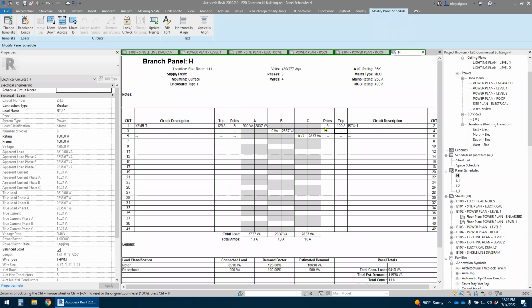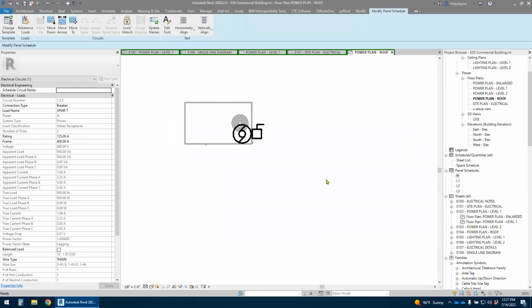I told you it wouldn't pull the information from anywhere. You also see that the way the family's set up, it's automatically dividing my load over the 3 phases. The transformer has a 900 and it's not splitting things up yet. So it's because there's only a 5 receptacle load. I don't think it would divide it over the 3 phases because it's only single phase loads on this 3-phase transformer at the moment. They all happen to be on phase A. Okay, close that one out.